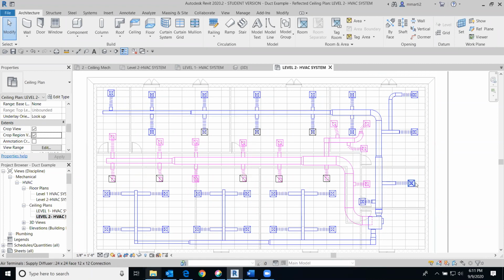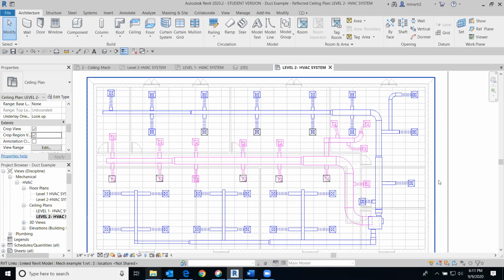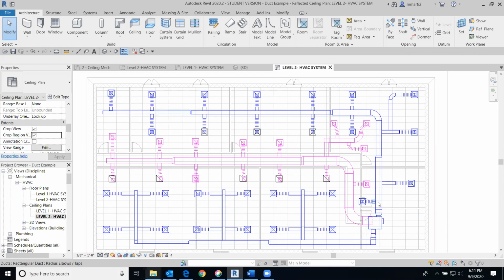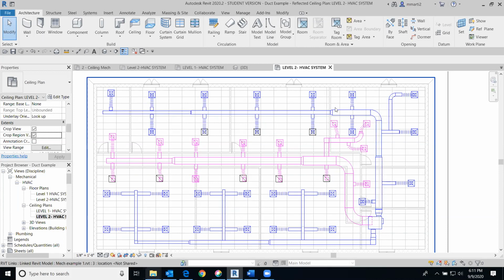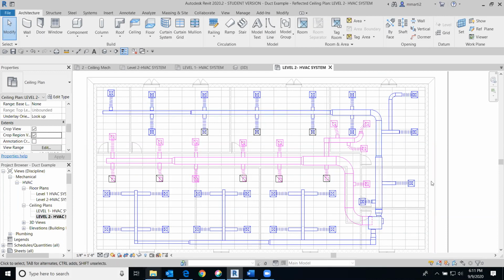So you're going to have a portion of the airflow here, but if you have this thick duct that runs all the way along this way, the force of the air coming out of this vent is not going to be the same as here. Either way that you think about it, the further away you get from the source, the weaker it is. So that's why we're starting with the larger ductwork here and constricting to smaller ductwork here. That's also a good reason that these curved ducts are used as opposed to a corner duct, because you have to think about the airflow as well.